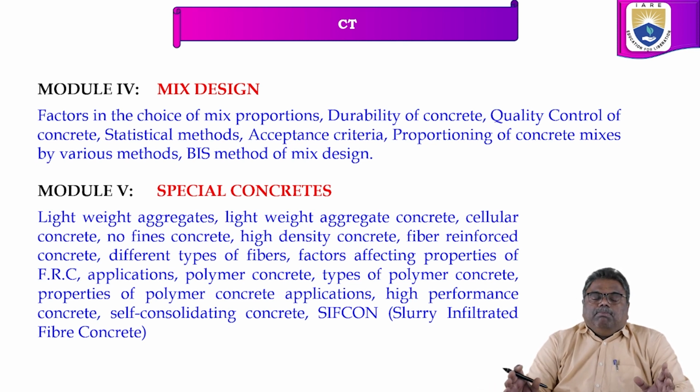Geopolymer concrete. Mineral admixtures means fly ash, GGBS. So these are the mineral admixtures. We will use these mineral admixtures to form the concrete by using polymer binders. So we'll use two different types of polymer binders. One is sodium silicate and the other one is sodium hydroxide.